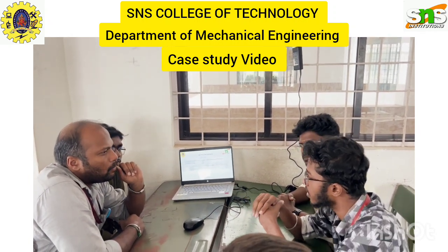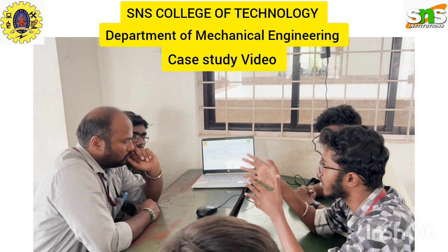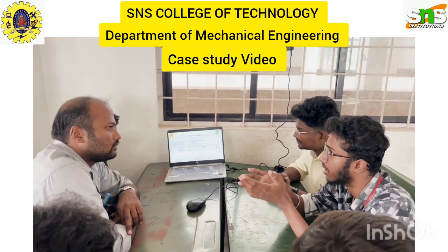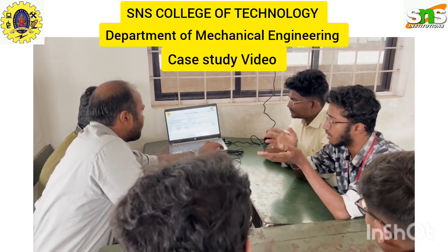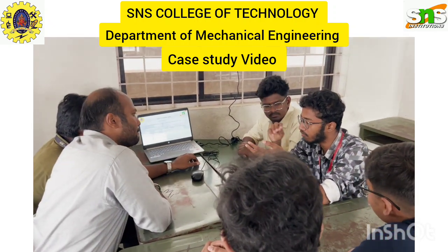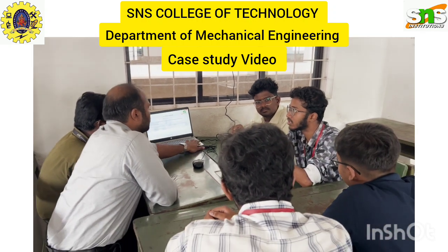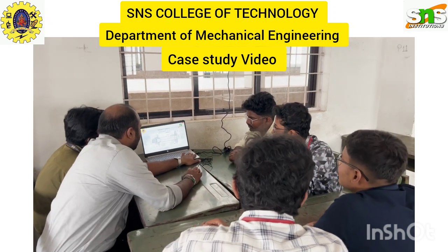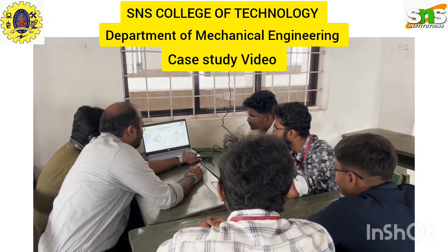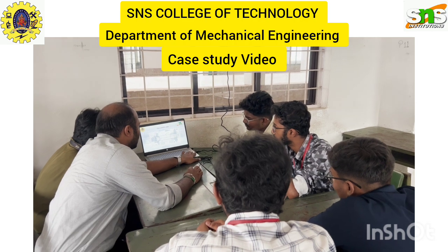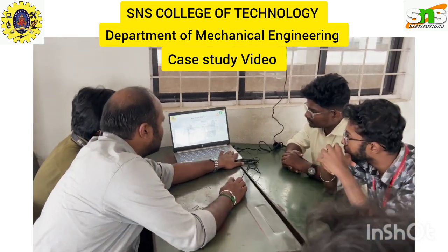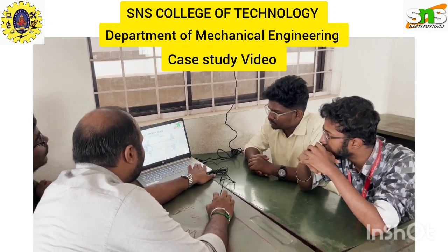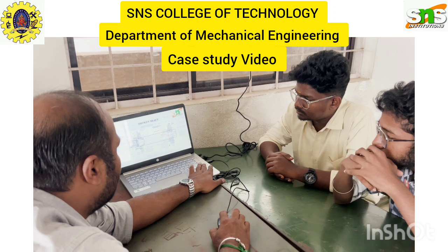Investigation. The failure occurred in the fillet radius of the drive shaft, which is comparatively smaller than the previously provisioned design. The shaft was quenched at a temperature that did not give sufficient hardness to withstand this. This is a diagram where this part is the failure part. The yellow and red color mark is the failure part. This is the complete drive shaft diagram, and the black area where the red color mark is given is the fracture plane, and this is the broken shaft.